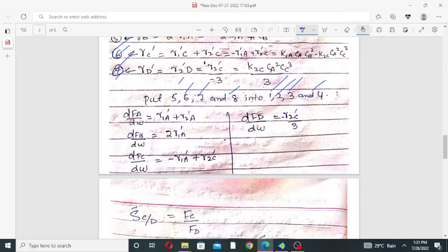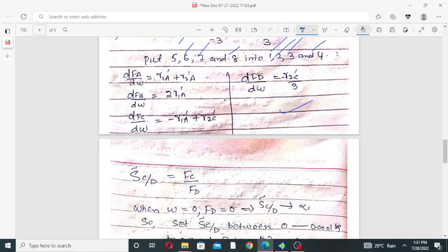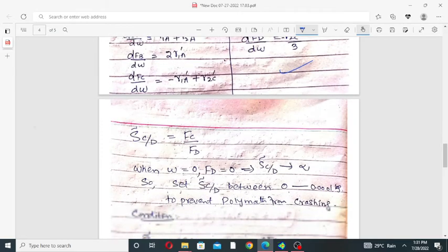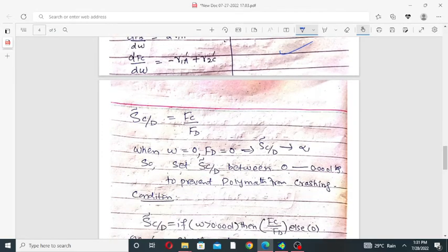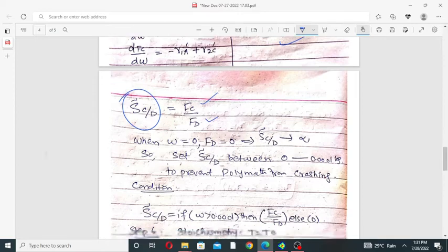So we obtained these relations when we combined the mole balance and the net rates of components A, B, C, and D. Then we know that the selectivity of component C with respect to component D in the flow reactor, which is the packed bed reactor, is the mole flow rate of component C divided by the mole flow rate of component D.